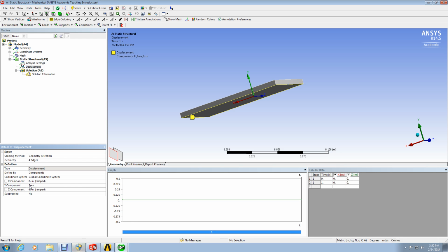So we only have the Y component displacement. Actually, it's the opposite. So this is 0. This is constant, and this is free, right? The Y is constant, and Z and X are free, right? So that finalized the fixture or the supports.